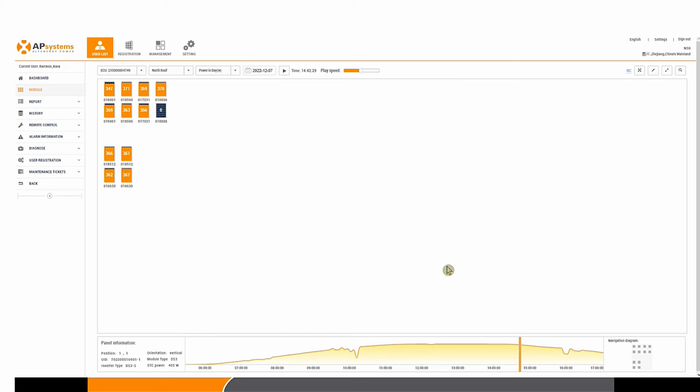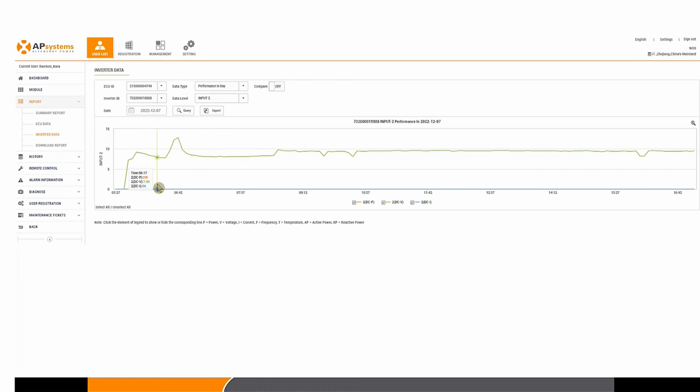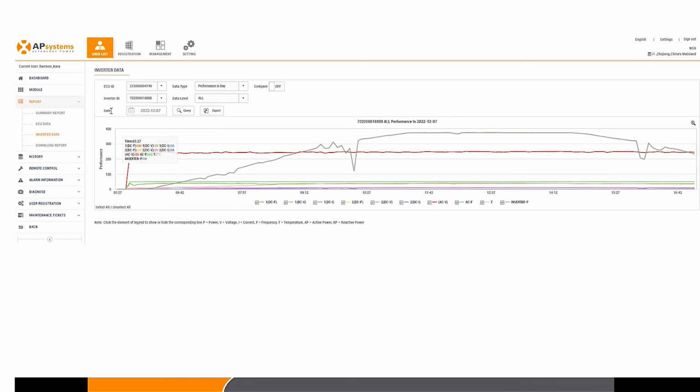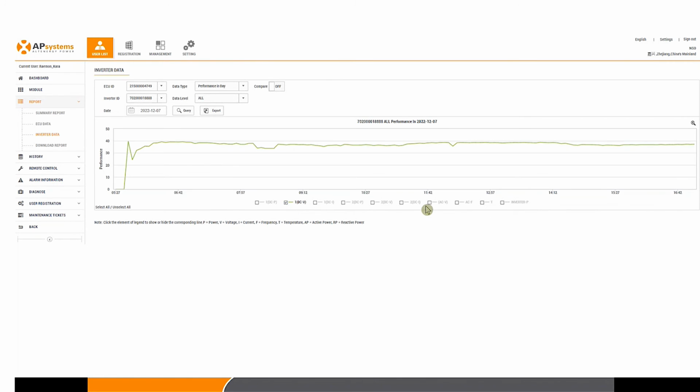Now, as an installer, I don't think customers can do this, but installers and myself with the admin level can actually go and click on this. We call this a channel. And then you see there's something called detail. You can see the stats. Now, you want to click on this and click on all. It will show both channels. What you want to do, the easiest way, is unselect everything because there's too much clutter, and compare the VOC of both channels.